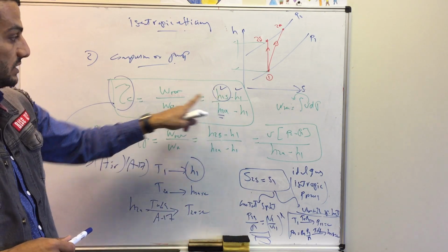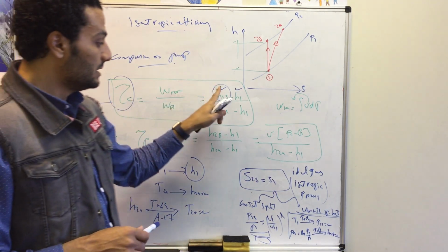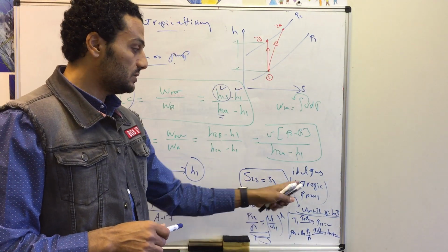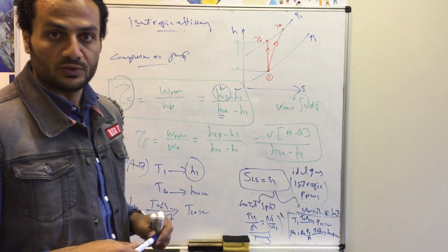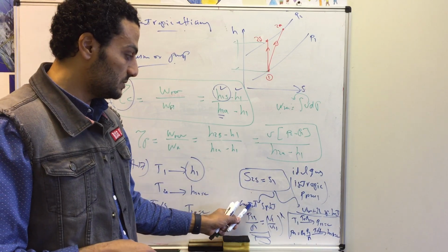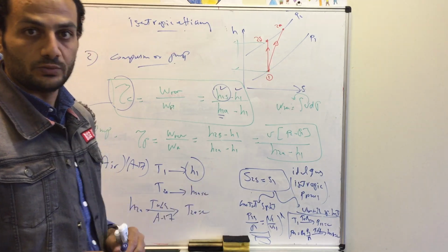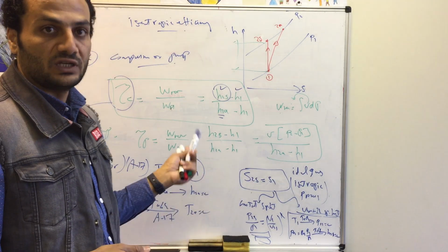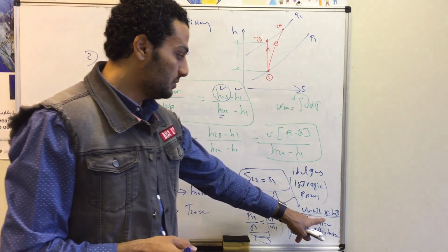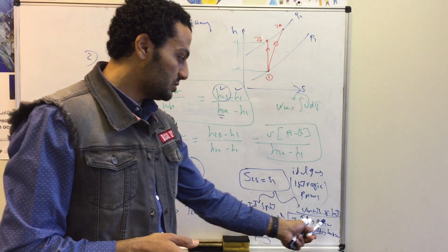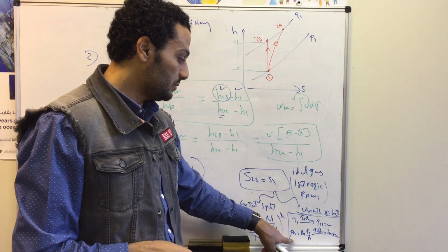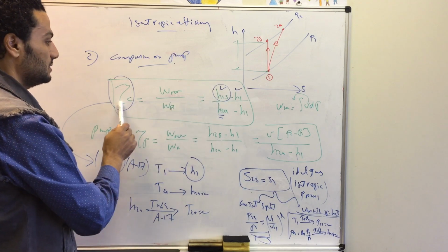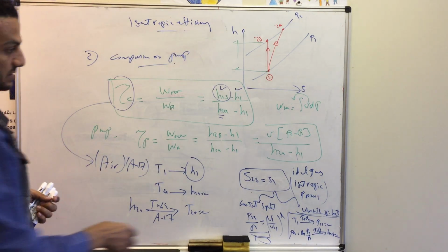And to calculate h2s, to calculate the isentropic efficiency, we do have s2s is the same as s1, so this process is isentropic, so we have an ideal gas undergoing an isentropic process, so we have to follow either the constant specific heat analysis, using the isentropic relation to get the value of the final temperature, and from the table we can get the enthalpy. Or following the variable specific heat analysis, at temperature T1 we can get Pr1, calculate Pr2, and go to the table again, calculate h2s. Then we can substitute here to calculate the isentropic efficiency of the compressor.